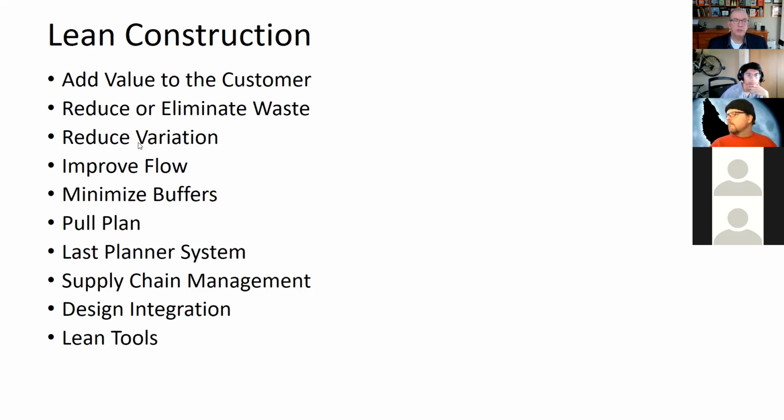Variation is where we start something and then we've got to stop and wait. So variation comes in where work is waiting for workers or workers are waiting for work. What's the point of rushing? Now you stop because now you've caught up. Now you've got to wait, or you've got to go off site to a different project, and maybe you don't come back, so you hold somebody else up. That is a stop-start kind of flow. So what you try to do with Lean is improve that.